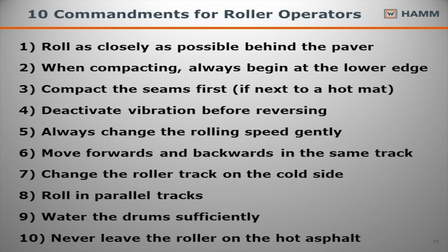Again, deactivate that vibration before reversing. We always want to change our roller speed gently when we're starting and stopping. We want to reduce that tearing of the mat or building of a bump. Want to move forward and backwards in the same track.